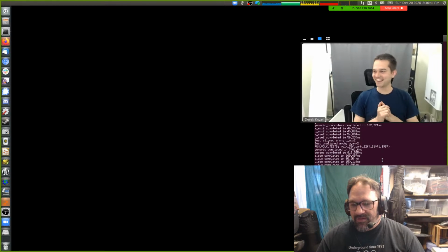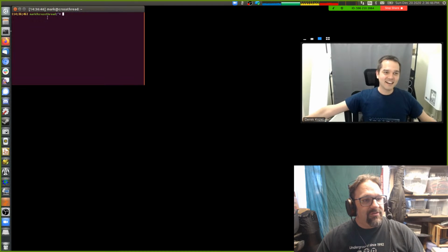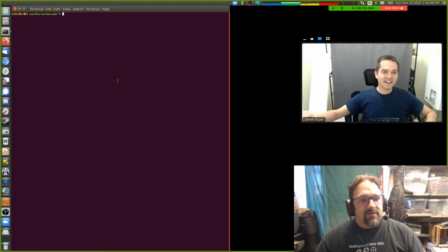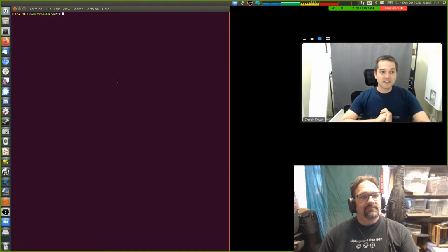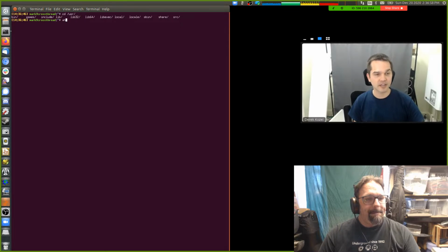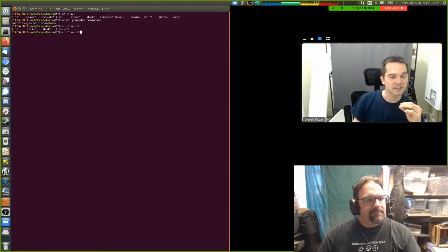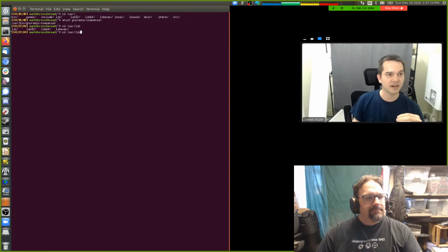All right, so it looks like my build completed, but I can't grab that because it's under the window, so we'll just do this. Where are we headed? Okay, so your install will be either in /usr/local or /usr. So can you type which gnuradio or -companion? Yeah, or dash, yeah. Okay, so it's in /usr. So we want to be in /usr. It'll probably be, no, so we need to grab the, look in the Python one, which I think will be in lib python something.